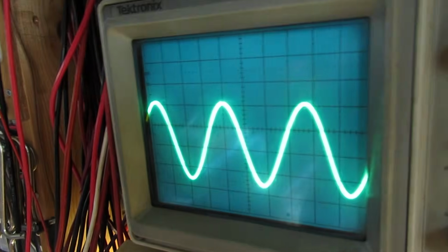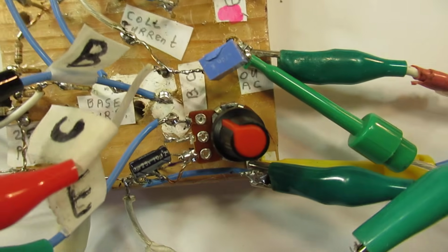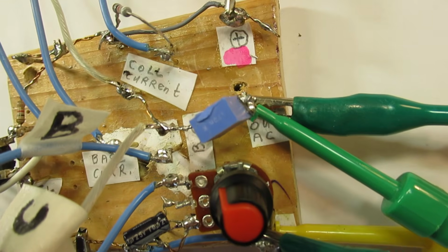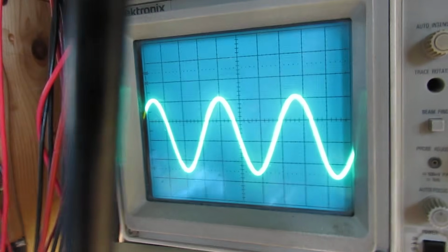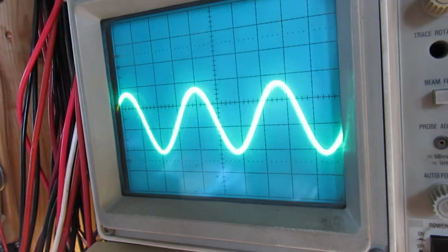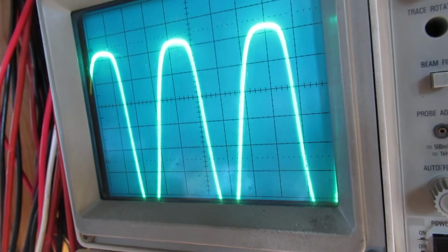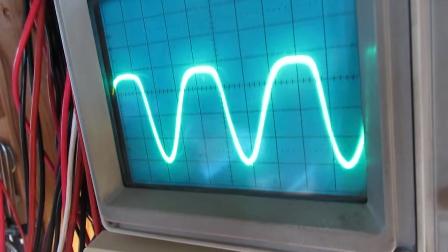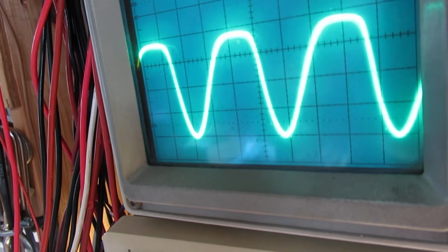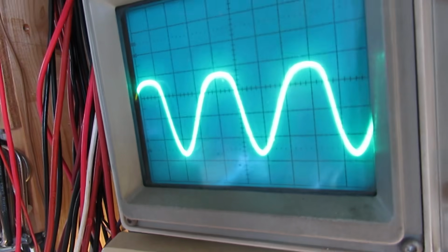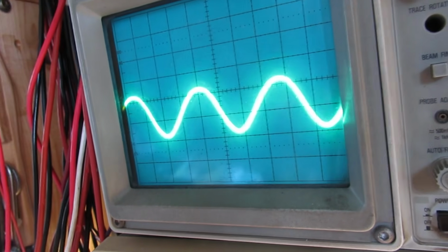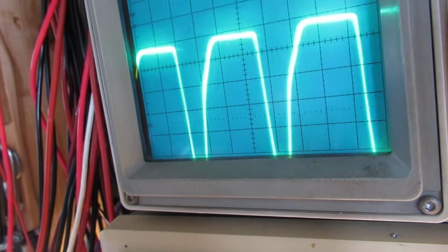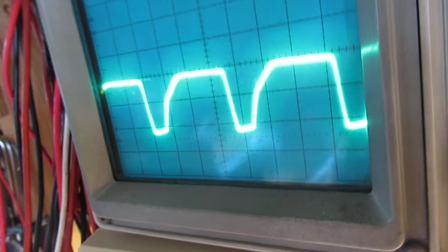Anyway, so what can we do more? Now I turn the 1 kilo ohm potentiometer in the emitter lead. Let's see what happens. It sets the amplification. You can directly see. And here we have over-amplification, and that means always distortion of the sine wave. I can make it better visible when I drive up the output level of the sine wave generator. Well, there is complete distortion, etc.